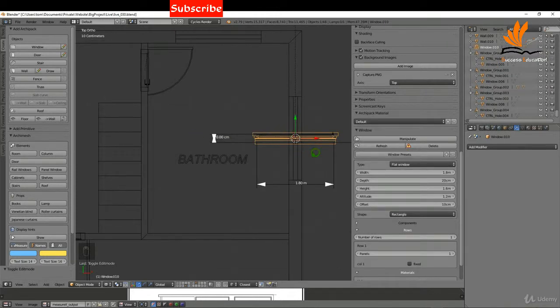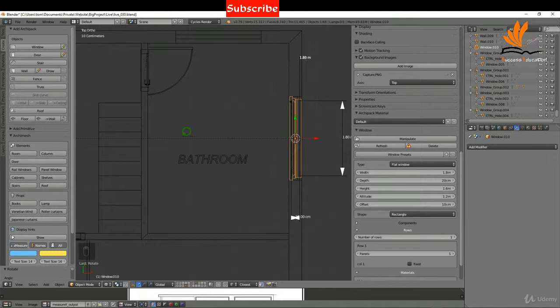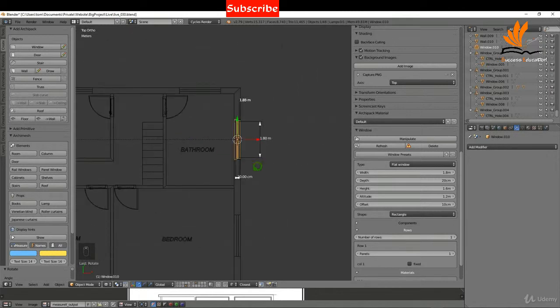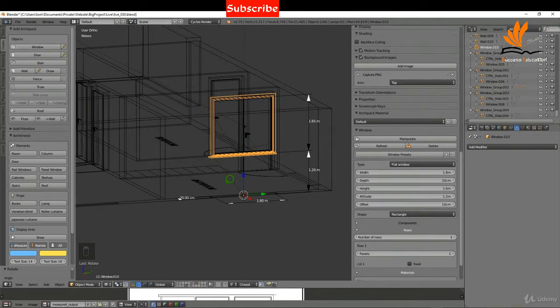Okay, so that comes in with my settings. So all I need to do is just rotate. So rotate on the Z by 90. You can see my light portal is shining inwards. Okay, so I can just come around here and I can have a look. So my height is a little bit wrong. So it's sitting a little bit too high, obviously.